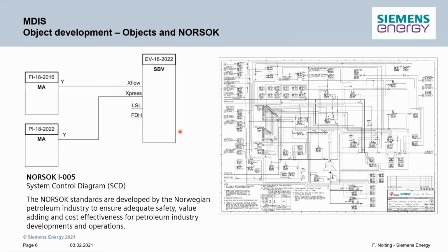The tag ID is used in our documentation. Here in the left corner I just wrote the NORSOK standard. NORSOK does not, for example, account for aggregates, so we have to make a more flat structure when you get into the control system. And on all our documentation, the tag ID will be presented.